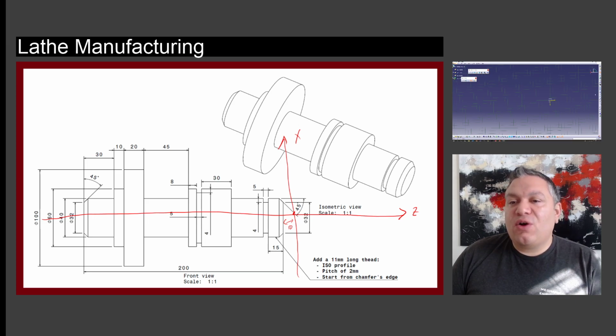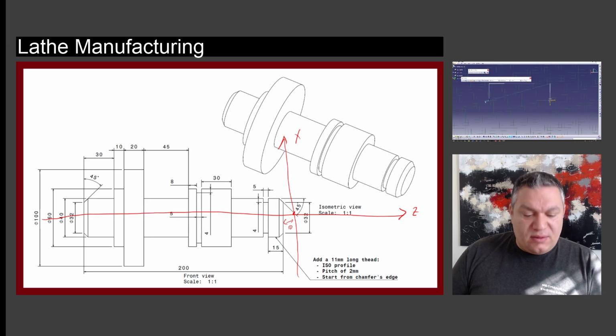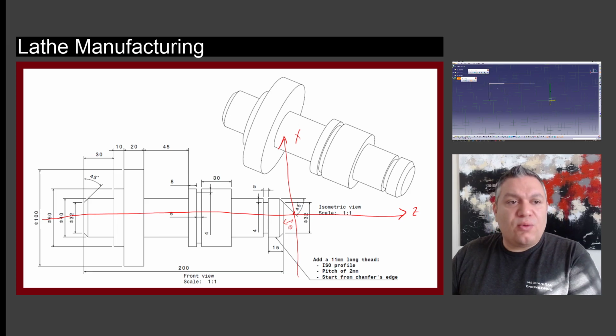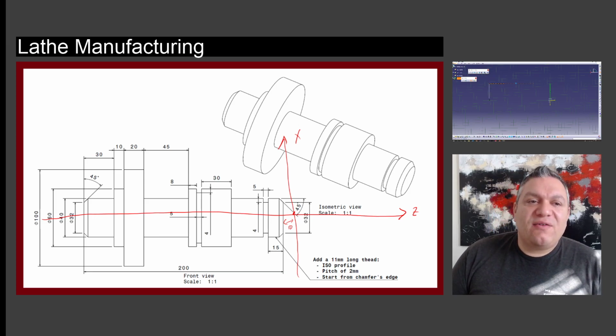So let's go ahead and create our billet. We're going to do a profile. The profile is going to go, what did we say dimensions? 120. So obviously 120, that's almost 60. We go back, we said 220, and we come down here. All right, so this is our profile. I did not have some of the things active, like the automatic creation of constraints. We're going to make sure that this is horizontal.